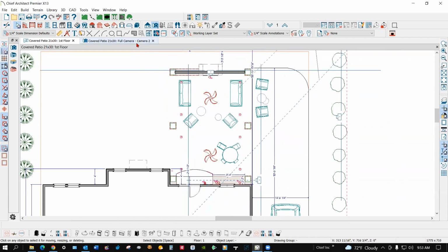Without a room specification dialog. See, trusses, when you create a truss, it fills the void between a room's ceiling and the underside of the roof. And there's no room here. So no trusses are possible.